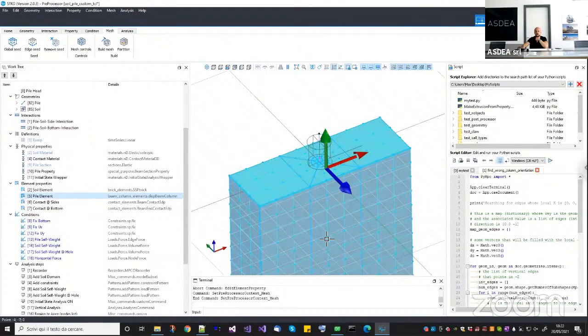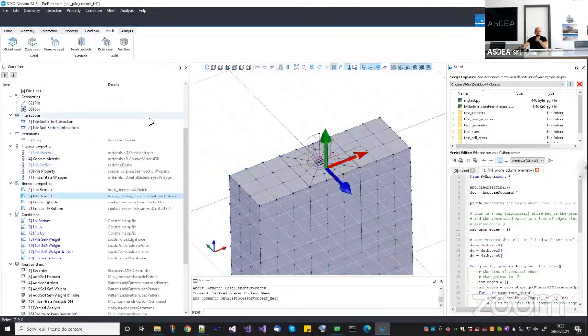So there are many pieces of pile, so you don't actually need a force beam column here. Now, in this case, this one is an elastic beam, so either displacement or force beam column is the same. And then you have other two contact elements, which are the beam contact 3D and beam end contact 3D.